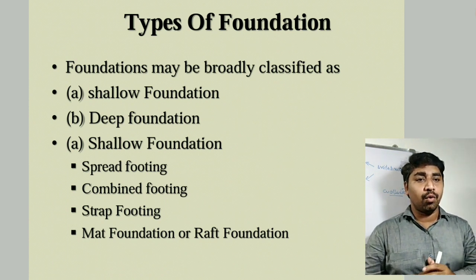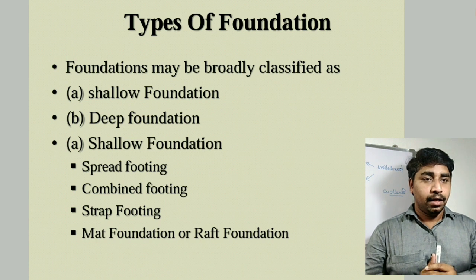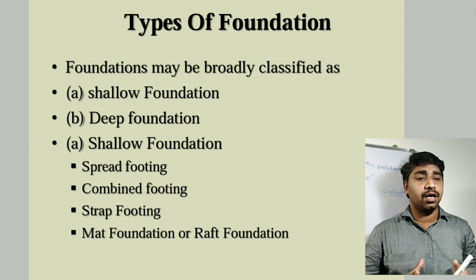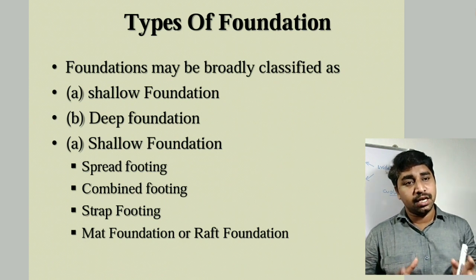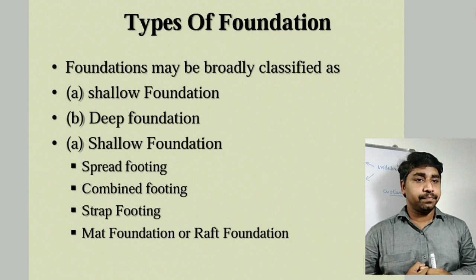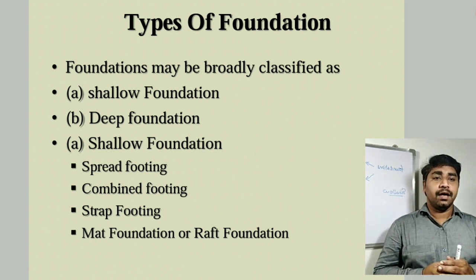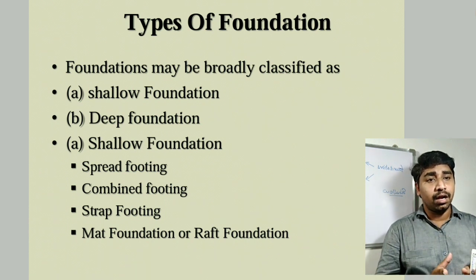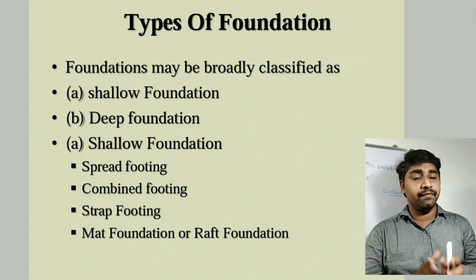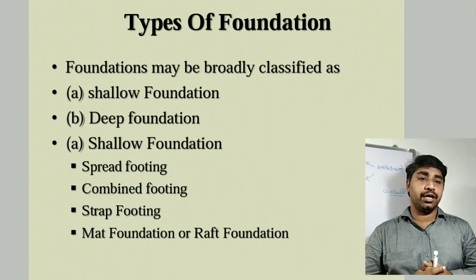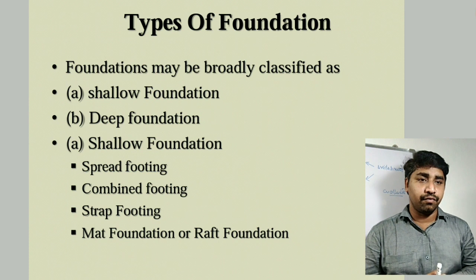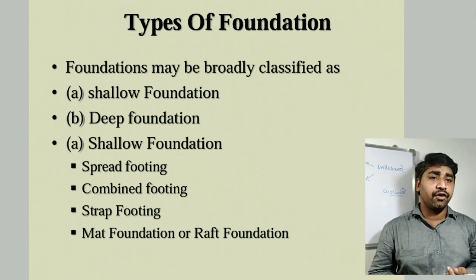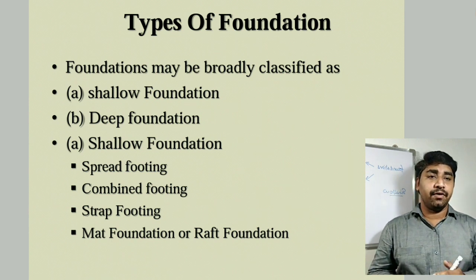What is a shallow foundation? A foundation laid at a shallow depth below the ground surface is generally referred to as a shallow foundation. Also, if the depth of the foundation is nearly equal to or less than the width of the foundation, it is said to be a shallow foundation. If the depth of the foundation is very large when compared to the width of the foundation, then it is referred to as a deep foundation.